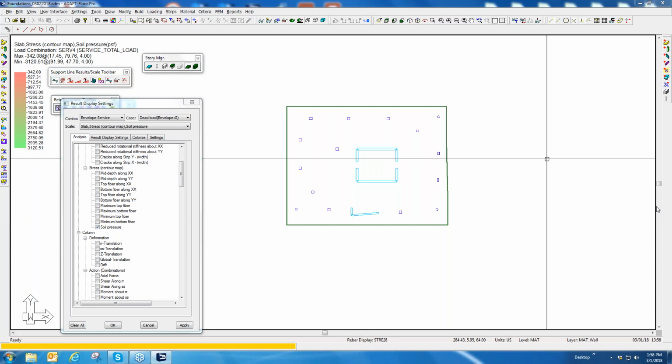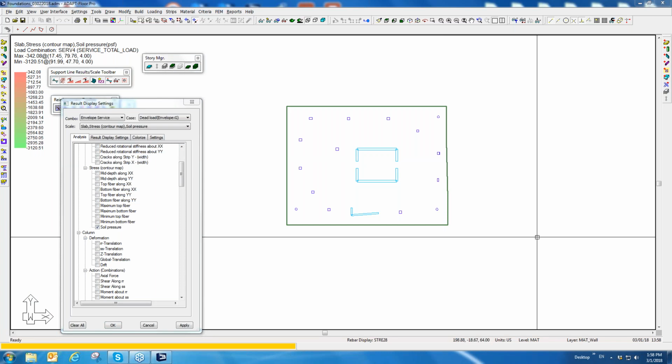The question is, there are many cases in ADAPT for calculating the rebar for strength combination, like over reinforced and under reinforced. Please explain. For the person that asked this question, I will send you a detailed technical note. But just in general, there are 6 unique cases that the program will consider for designing a section for strength. Number 1 is if the capacity of the base section is less than the demand, the program will simply add reinforcement, and it will always also check ductility.